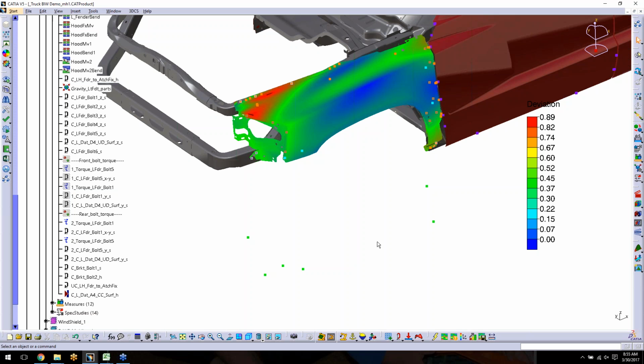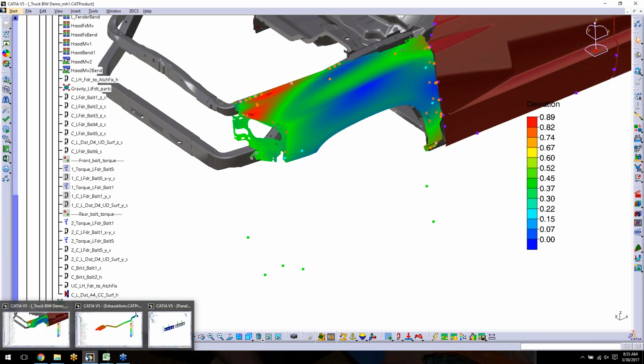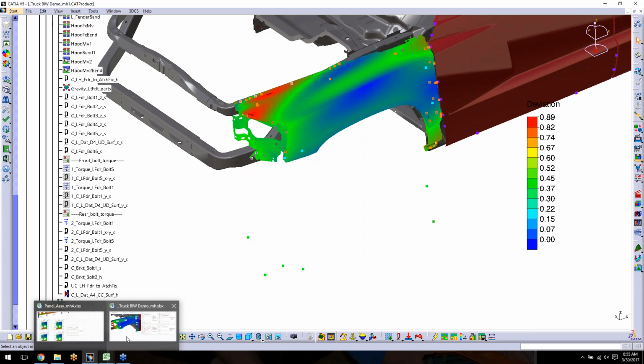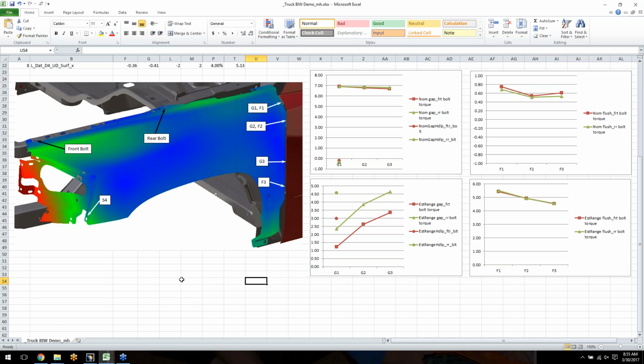So our compliant moves change your nominal position of your parts. Monte Carlo analysis is then run using the new nominal position, and that compounds your part and manufacturing tolerances with your compliant moves. So yes, everything comes into play. Your rigid moves will put the parts in their nominal. The compliant moves depend on what they do, but yes, they will change the nominal of your features in certain areas, because they twist the parts.